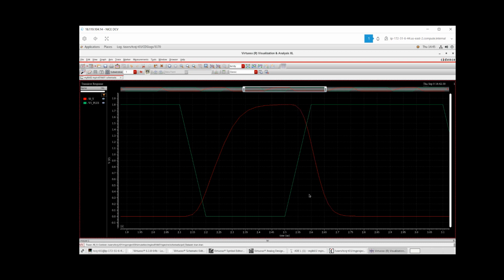So we know that the NMOS is normally stronger, especially for these smaller default size transistors. We know that the NMOS is stronger, so it's going to be a bit faster on the high to low transition caused by the NMOS. So now we are happy with our simulation. Let's say that we know that our design works.